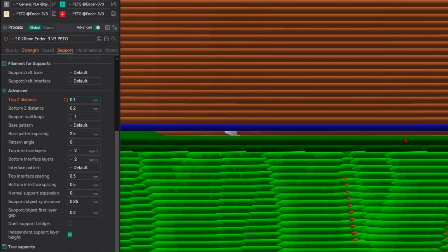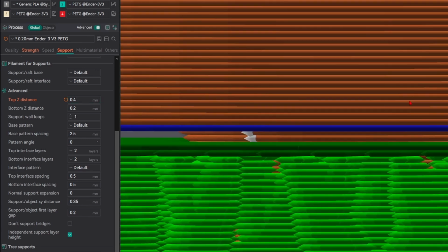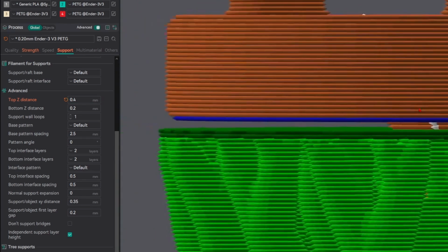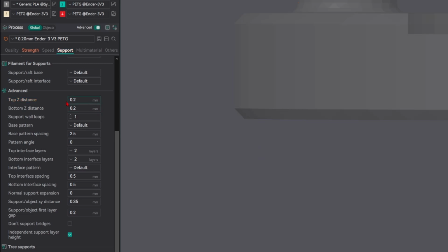So most of the time it's going to stick to your 3D printed part. So I'm going to put it to 0.4 and see the differences here. Like that, the gap is a lot bigger. And by doing this, it's kind of bad because this is still like an overhang here. So as it prints, the filament is going to sag down, touch this, and bond with it. So it's quite bad. Leaving it at 0.2 is good. Maybe if you want to, 0.21, 0.18, stuff like that.